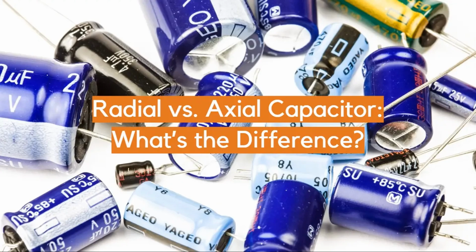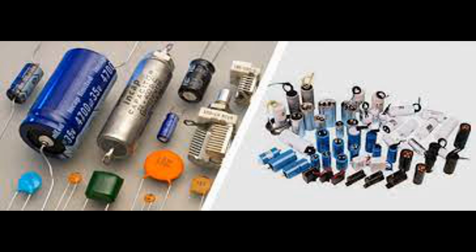Aluminum electrolytic capacitors. Aluminum capacitors typically have higher ESR compared to tantalum capacitors. The ESR of aluminum electrolytic capacitors can limit their performance in high-frequency applications. Higher ESR can lead to power losses, reduced filtering efficiency, and increased heat generation.